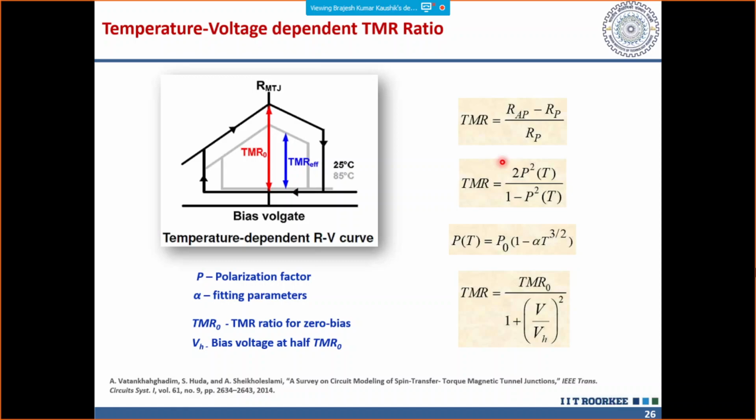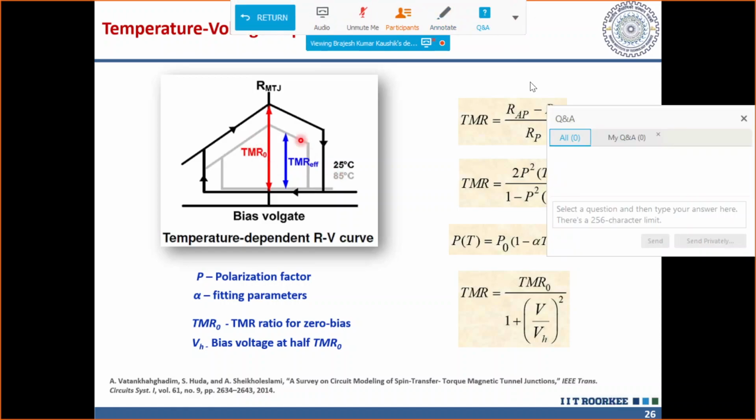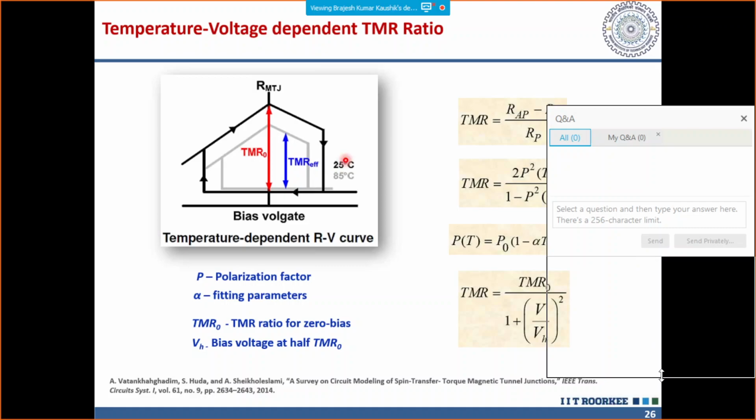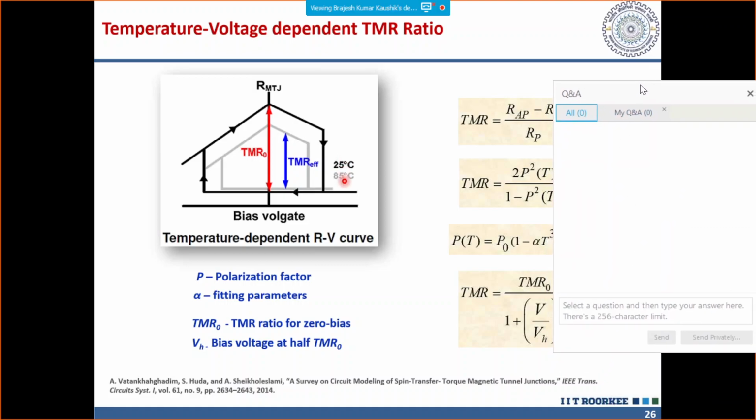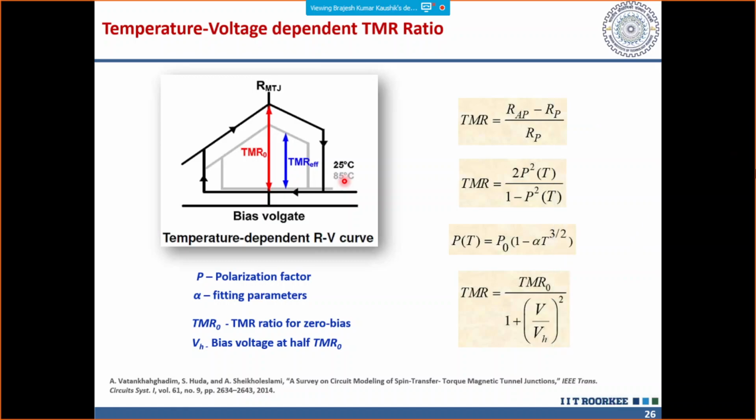But then things did not move well, because most of the devices that we had based on spintronics were highly dependent on the ambient temperature at which they were operating. If you see the TMR ratio, it drastically changes as you increase the temperature. And I think it's very important to understand that we cannot manage to change the TMR ratio too much, because if you change the TMR, that means the difference between the two states is not really distinguishable.